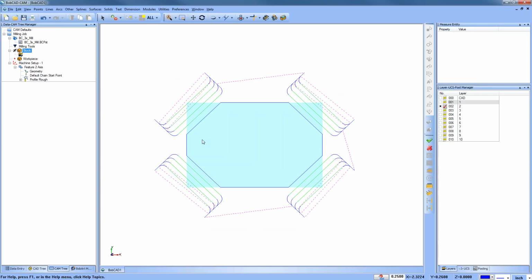Now, the downside of using side roughing like this is it's not as efficient of a tool path. If we did an open pocket, like last week's webinar where we talked about the advanced pocket and open pocketing and working its way in from the outside, that one would be trimmed to the stock material, where you can see with this one here, we're getting wasted tool motion. Okay, so again, you have to look at the right tool path in the right scenario.